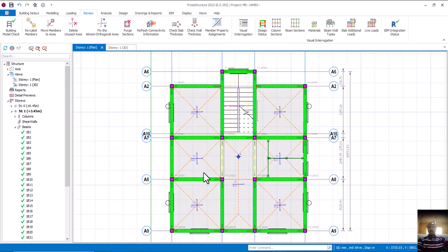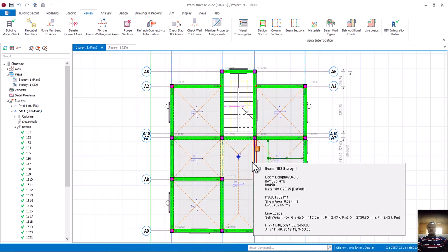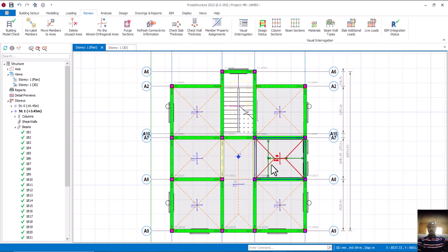And once you have hinged like this, and you have done your analysis and design, and you have done your detailing, the engineer at site, all he or she needs to do is to go ahead and execute based on the information that has been provided. Is that okay? So that is that. You don't hinge at site. You have no business hinging at site. Where you do your hinging is what is in your design, during your design, or during your modeling. That's where you apply hinging. Is that okay? All right, that is fine.